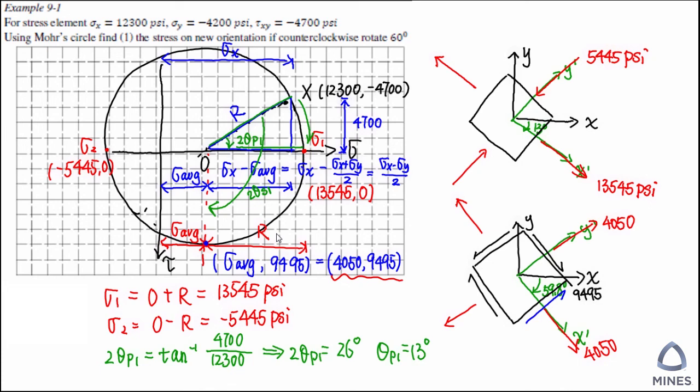So be very careful here. If we were trying to only draw the principal stresses, you can see we don't have any shear stress on the principal stress plane. However, on the maximum shear stress plane, it all depends on whether the center of your Mohr circle is 0 or not. If the center of your Mohr circle is at 0, then you don't have normal stress. However, if the center of the Mohr circle is not at the origin, you have to show the normal stress on the maximal shear stress plane.